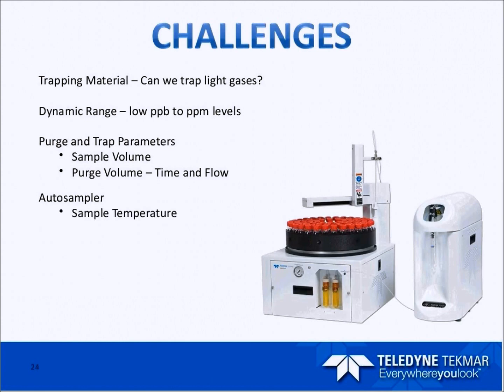So with the auto sampler, do we need to chill the sample or not? How cold do we need to keep it, things like that. The sample temperature, as we found out going through this, was actually one of the most vital things. If you think about it, when you're making a saturated gas standard at 0 degrees, you let that equilibrate to room temperature, and as soon as you pierce that, that's become a supersaturated solution. So that can lead you to crazy issues with reproducibility.